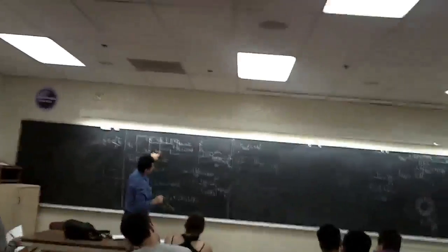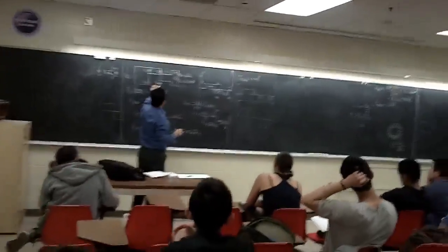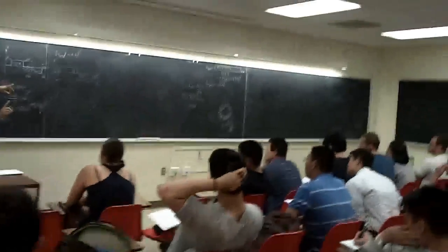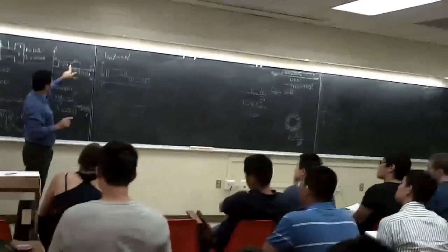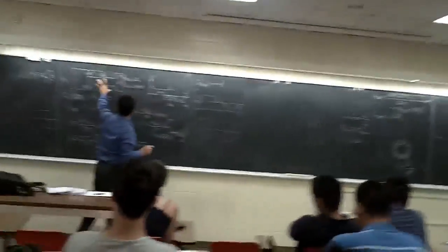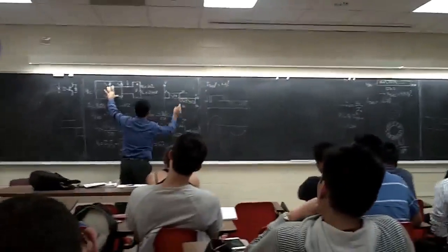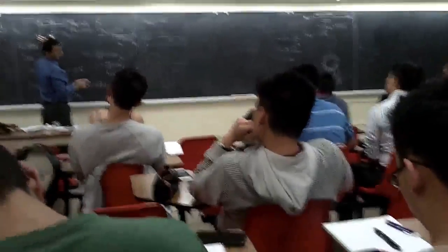So, let me see. We have S1, S4, and we have 0 voltage. So this is the way I'm going to have the minimum switching, minimum transition, see? S1, S4, right? To have the 0 voltage here, either I could have S2, S4, or I could have S1, S3, right? But I'll go with the S3.